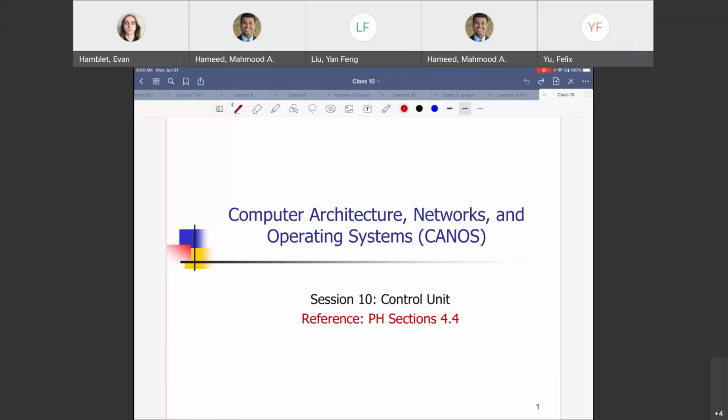We are going to include the jump instruction first, then talk about the control unit, because there has to be some hardware that is able to look at the opcode field of the instructions and also the function code field, and tell all the muxes to pass one thing or the other, and also tell the ALU to perform an add operation, subtract operation, and so on, right?